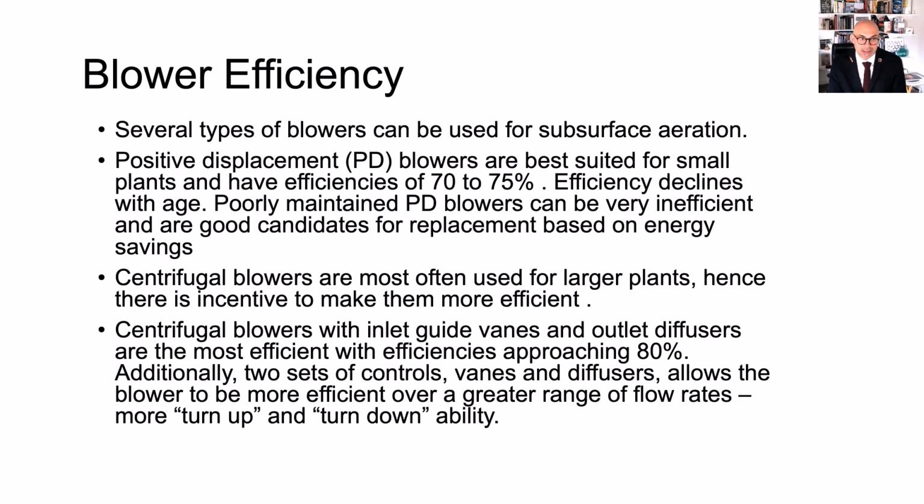Now, centrifugal blowers can also be tuned in their airflow, not by changing the speed necessarily of the rotor, but by keeping the rotor at fixed speed and changing these little vanes. There are little blades that can curtail the flow going in and out and regulate the pressure with a control system. And so you have the inlet vanes that open like a fan and close, okay? And these little blades can regulate how much air goes into the blower.